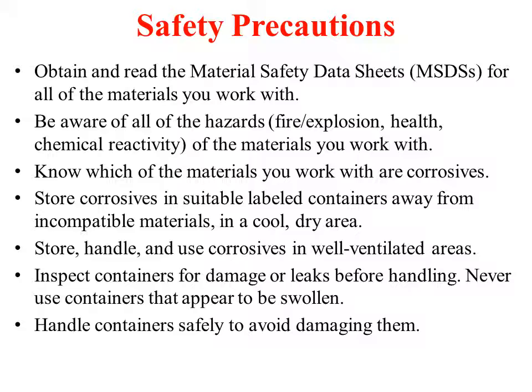Next point, corrosives should be stored in suitable labeled containers away from incompatible materials in a cool, dry area. So whatever corrosives are there in containers, they should be labeled properly, and the label should provide information regarding the type of chemical, the hazardous nature of that chemical, and so on. And it should be stored away from incompatible materials.